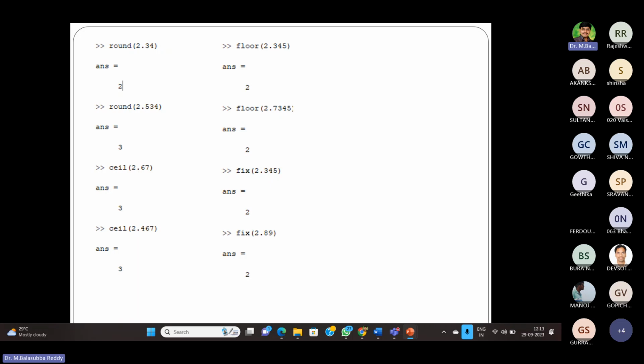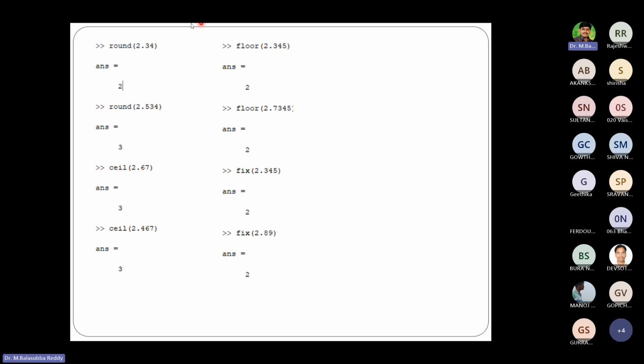It cannot be fractional, it has to be an integer number, whether I have to use 3 SCRs or 5 SCRs, like that. It is a count. That is the reason it should always be on the upper side. Otherwise, what will happen? It will go for an overload case. Even if it is 0.1, the load is going to be overloaded. It should not overload at any point of time. That is the reason in those cases we can use ceil.